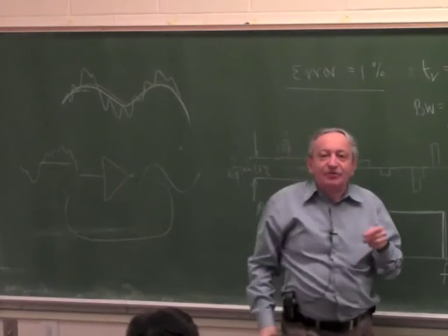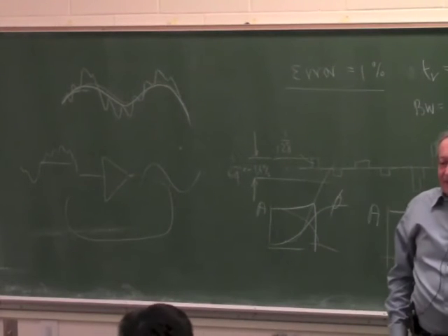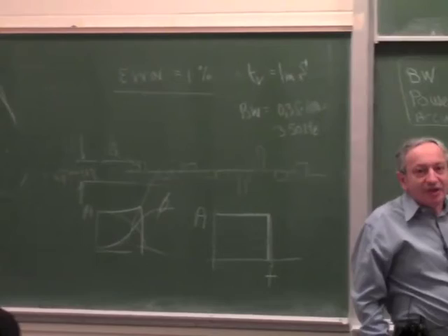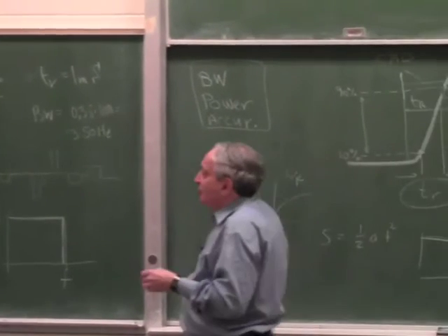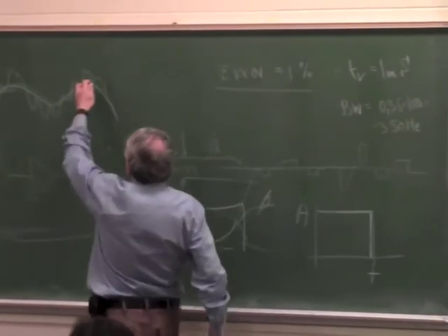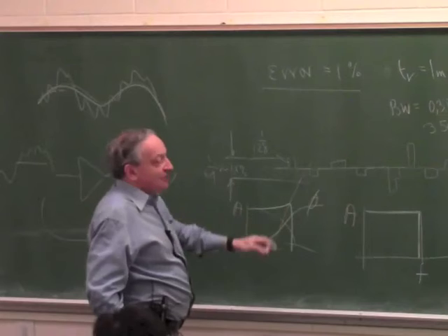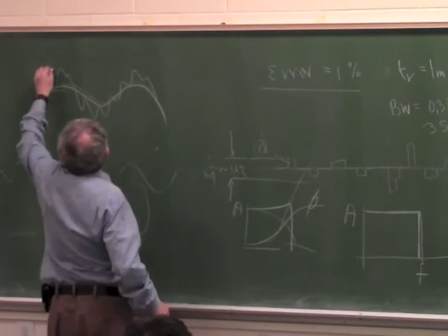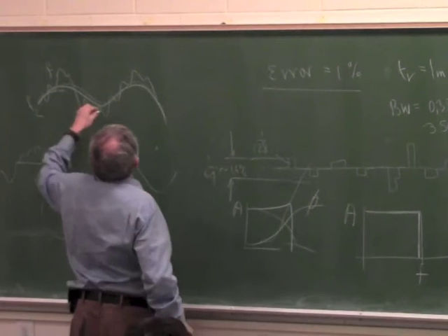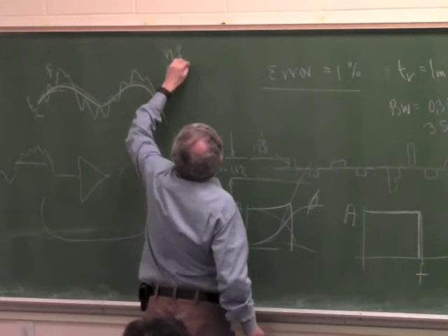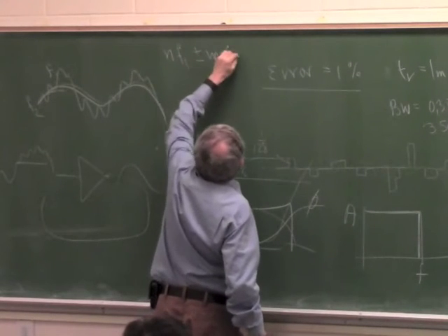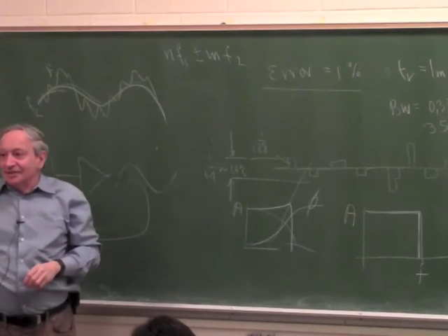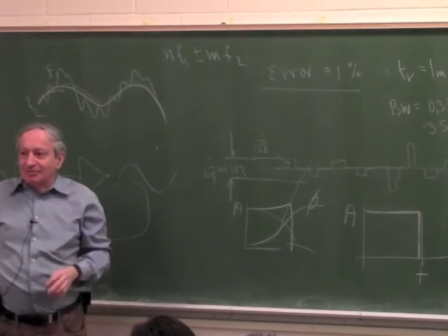And how can a new frequency be generated? Because of nonlinearity. Very good. Because I went over it, that in a nonlinear system, if you put in frequencies f1 and f2, at the output you can get the sum and difference. Actually, if you put in f1 and f2 in a nonlinear system, you can get nf1 plus or minus mf2, where n and m are integers. Okay?